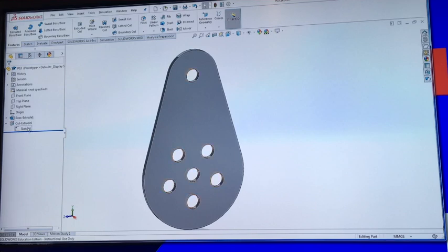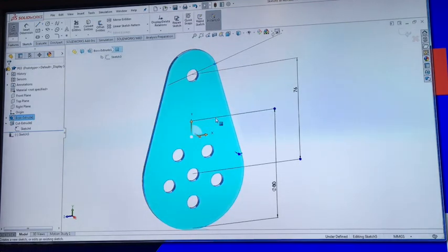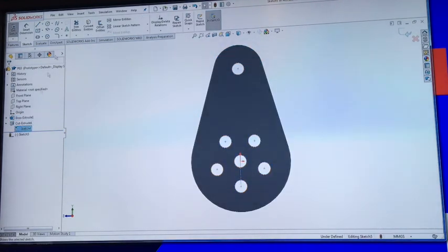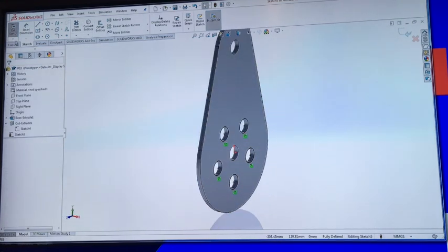Well, the pattern is part of the sketch that is part of this cut extrude. So I would have to go in and edit the sketch, but as we saw, editing the sketch will affect both configurations because it has to be on to keep the A and B hole. So my design intent here is to fill in the 5 holes that are the pattern. What's an option to fill them in? You could do a whole other sketch which was exactly the same thing but like a negative version of it. That was just like 5 cylinders extruded to the same depth.